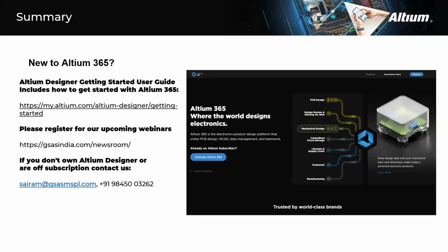Yes. To summarize today's session, we have showcased how the new simulation dashboard helps you perform simulation, how easily you can add the model file, how you can map your schematic and the model pin mapping, and then how you can do the verification process. Later we showed how you can perform the simulations: operating point, DC sweep, transient, and Monte Carlo analysis. And we showed you how we can connect with your colleague through Altium 365 for reviewing your design. Yes, this is all about today's webinar on SPICE simulation made simple.